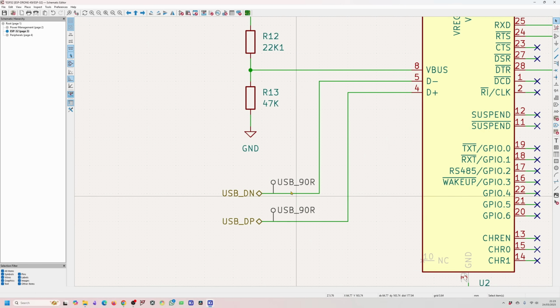And the reason this is slightly better is that if you print off the schematic for review and someone else is looking at the schematic itself, then they will be able to see the directive as well. Whereas the other way we just did, it's only visible if you are looking at the schematic in KiCAD, which is not always possible. The schematic might be reviewed by someone else, and they may do a paper review rather than a review on the software.